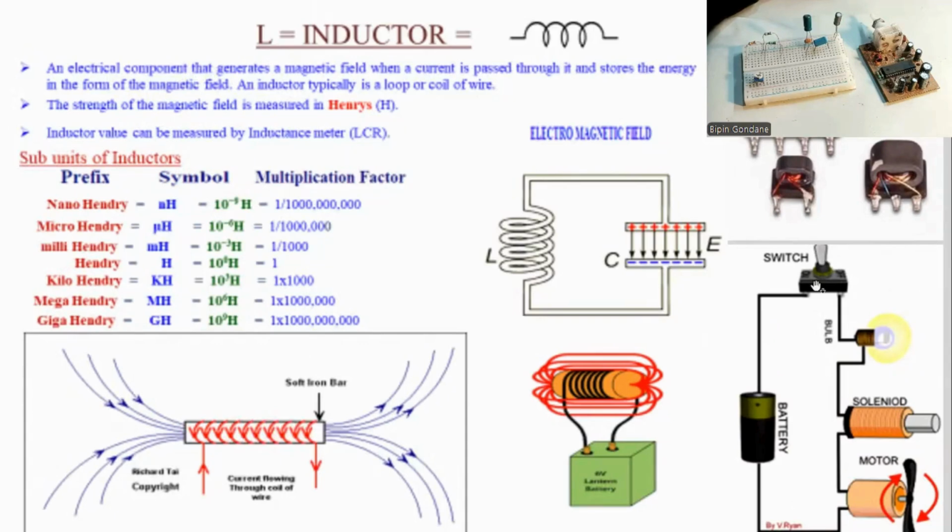As you can see here, the best examples are the fan motor and the solenoid. Okay, I have just shown it here. And for inductors, the next stage is also about transformers. So I have just indicated here these are the different values. What are the values? That is Henry. Henry is the unit of inductance. Please remember, V is equal to L multiplied by di, that is the current, divided by dt, that is the time. Okay, what is its work? Why is it used?